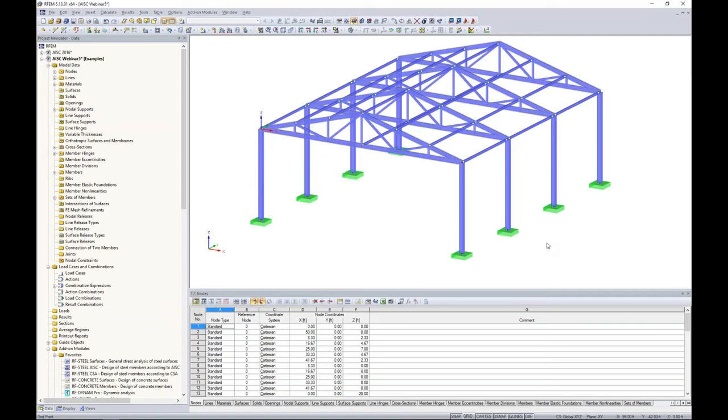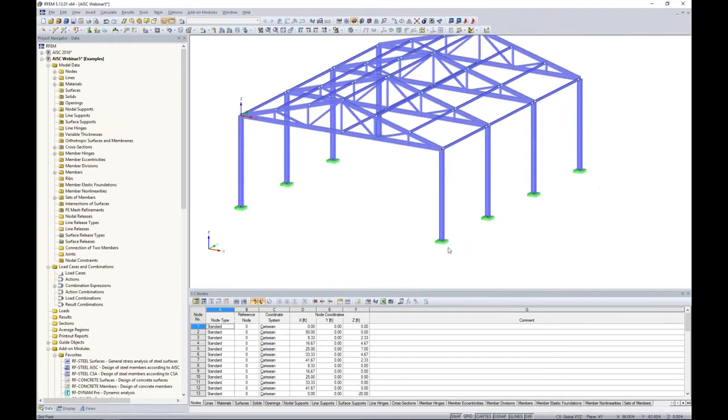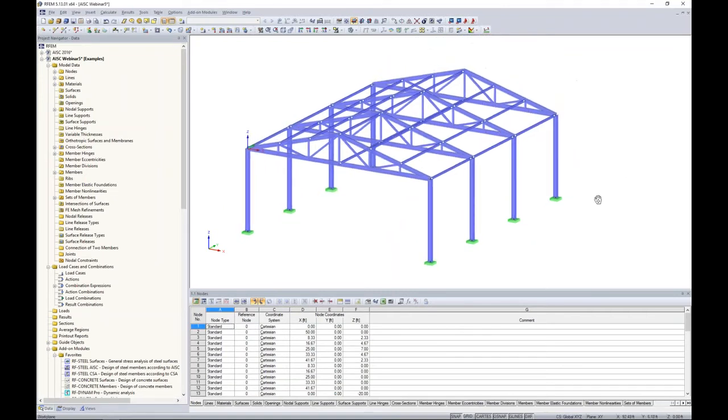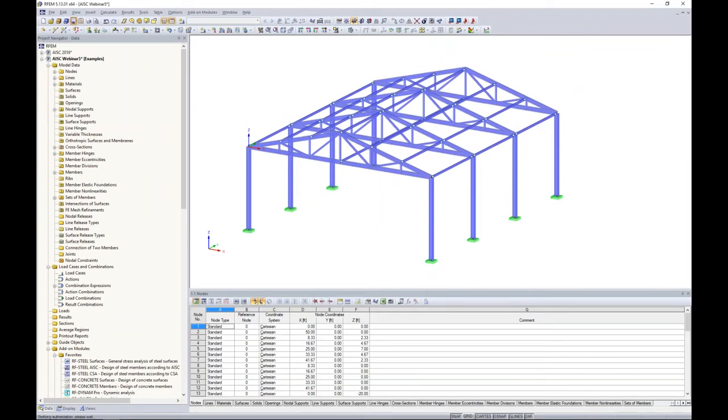Now, if I think that, okay, the supports are maybe a little bit too big for this structure, what's nice is that I can always right-click on these supports to decrease the size. So now you can see all of them are a little bit smaller in size. And the same thing goes for loads applied to our structure graphically as well, just something to point out there. Okay, so the geometry and the supports are completely done for our structure, so we want to move on to loading.